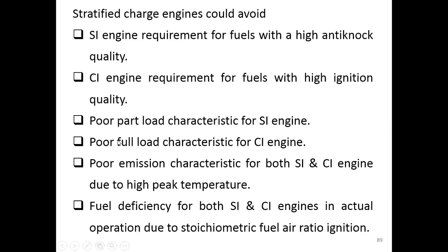This stratified charge engine can replace this characteristic of the CI engine. And also the poor emission characteristic of both the SI and CI engines due to high peak temperatures, because they go for the stoichiometric ratio.